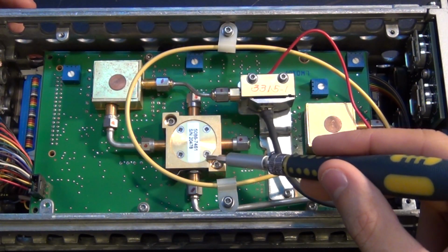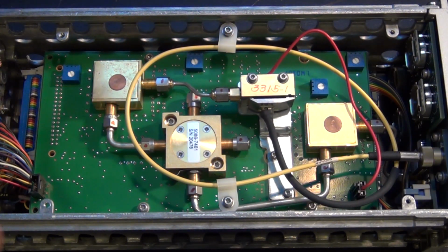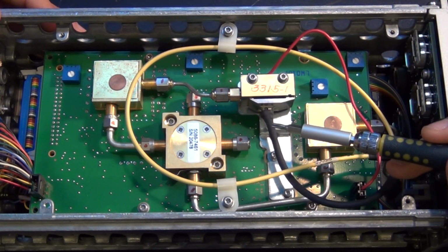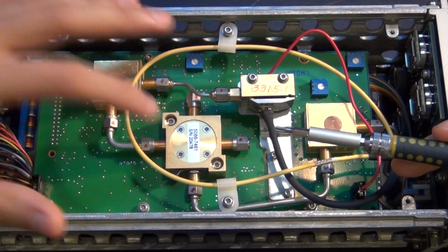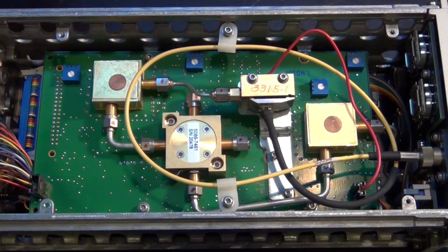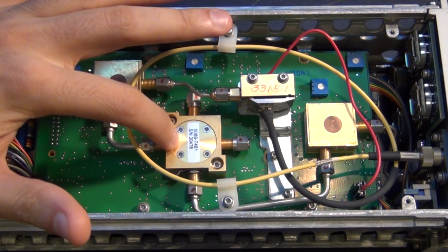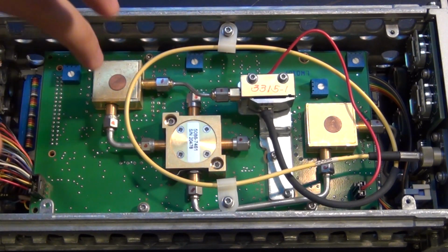So why is this so important? Well, if you think about it, you cannot in any reasonable way send a very, very high speed impulse train, very, very short rise and fall time to this module from the mainframe. You have to generate it locally. So the trigger signal, which has very long rise and fall times, it's like a big square wave coming in at low frequency and very, very long rise and fall time, goes into this module and becomes an impulse train with exceptionally narrow width of pulses. And that's really important, because the width of this pulse will determine the ultimate bandwidth of the sampler.